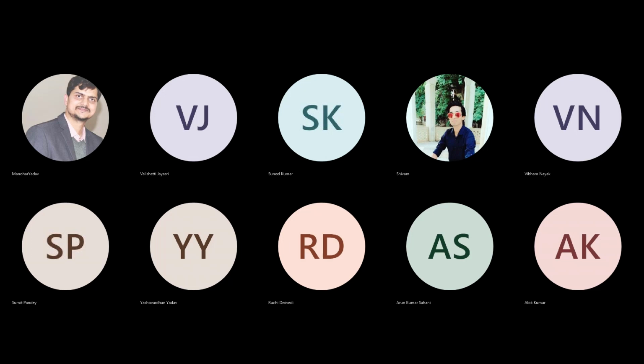If you point somewhere on the screen with a pointing device and switch it on, the laser footprint is projected on the screen, and it has a size a bit larger than the diameter from where it is generated. That is due to the spreading in the medium as the laser travels through it. So what is the requirement in the case of EDMI as well as LiDAR? The laser source should be directional and sharply focused.